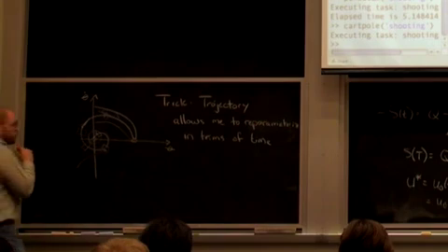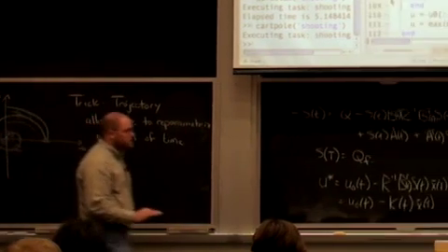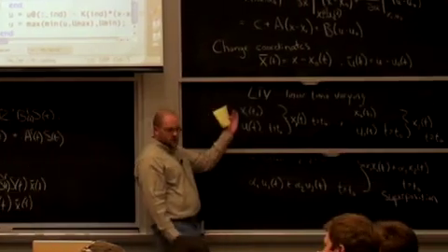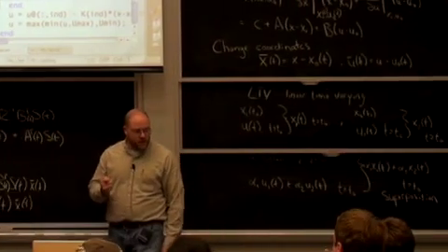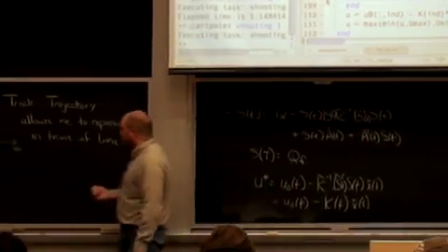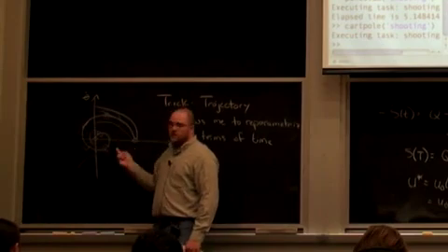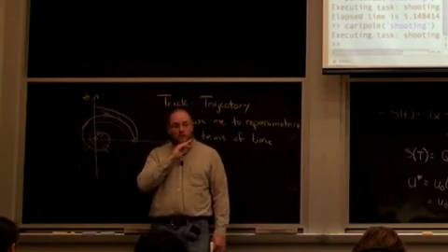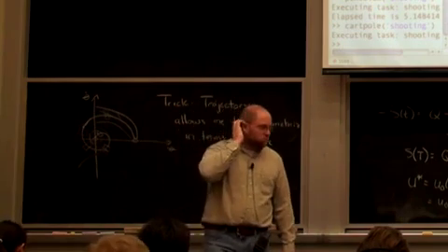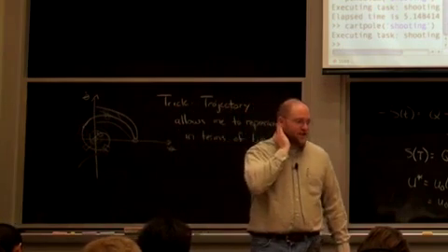Okay, so big idea: turn my nonlinear system into a linear time-varying system because I've reparameterized it along the trajectory, do linear time-varying control, and even really complicated systems, that'll work well. We're trying to do it on our perching plane. We're doing it. I mean, it's really a pretty good idea.